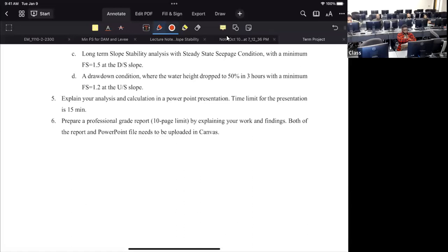How can you create a climate adaptive infrastructure system? You don't have enough money to demolish the dam and build something new, right? So you have to make an efficient discharging system. Whenever you have those conditions, you just need to let the water go away. You let it flood because that creates less problem than the overtopping, which will be devastating.